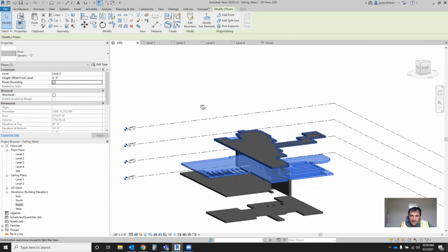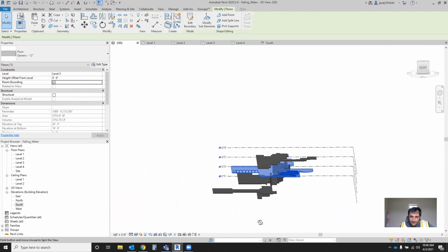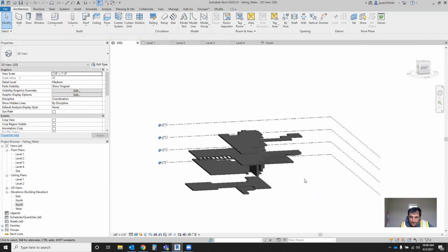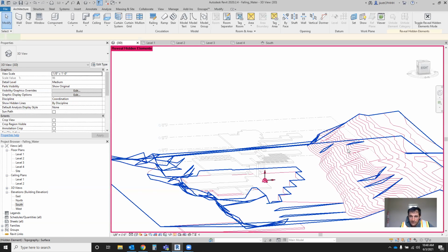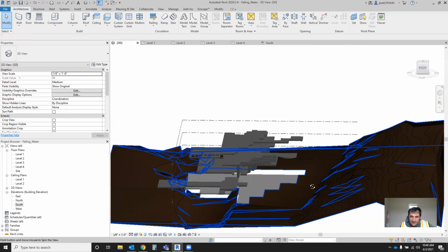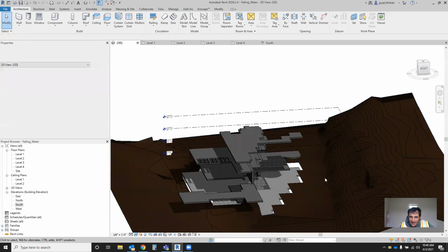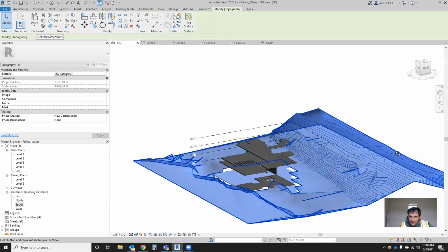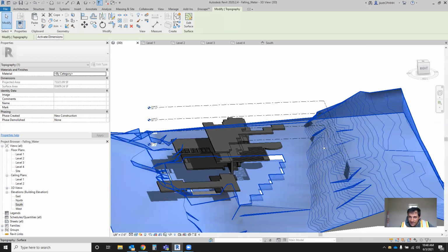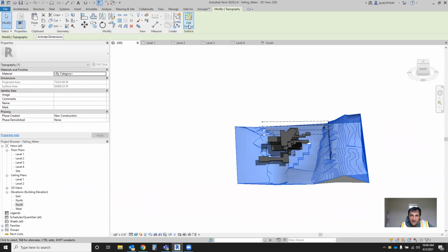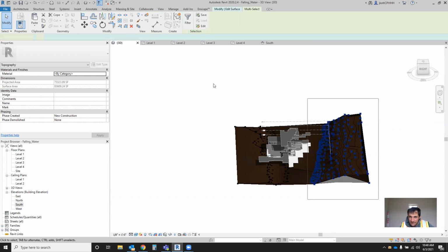But now you can see how this driveway area interacts with the rest of this model. If we turned on our grade, you can see that our model is not interacting with our topography correctly. So we are gonna have to spend some time fixing our topography because this hill should be embedded in this wall. And we might be able to just adjust this surface like this.